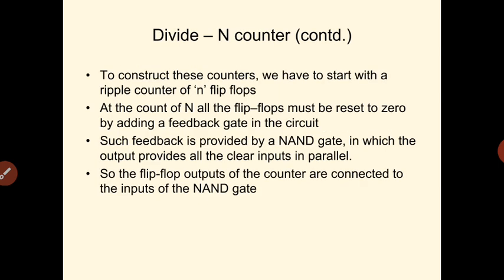To construct these divide by n counters, we have to start with a ripple counter of n flip-flops. At the count of n, all the flip-flops must be reset to 0.